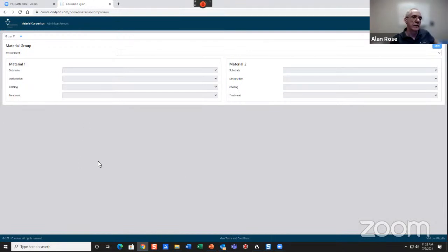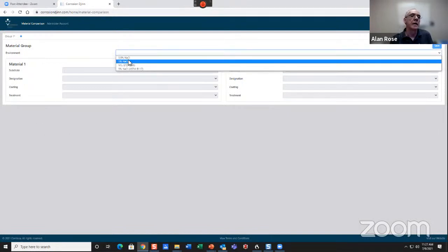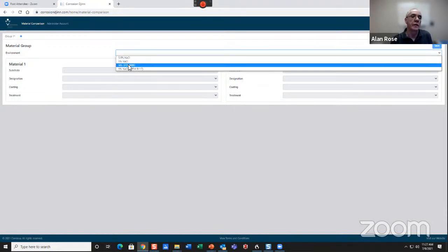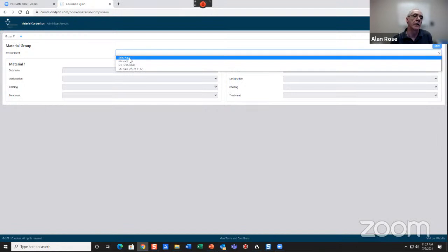So let's assume, for instance, the scenario is your M&P engineer is interested in the issue of fasteners, just like on the F-18, the aluminum structure, and reducing galvanic corrosion risk. So we can choose the environment. I'll choose a 3.5% sodium chloride as a marine type environment. We'll be able to do the MIL standard 889D data as well when that comes out.